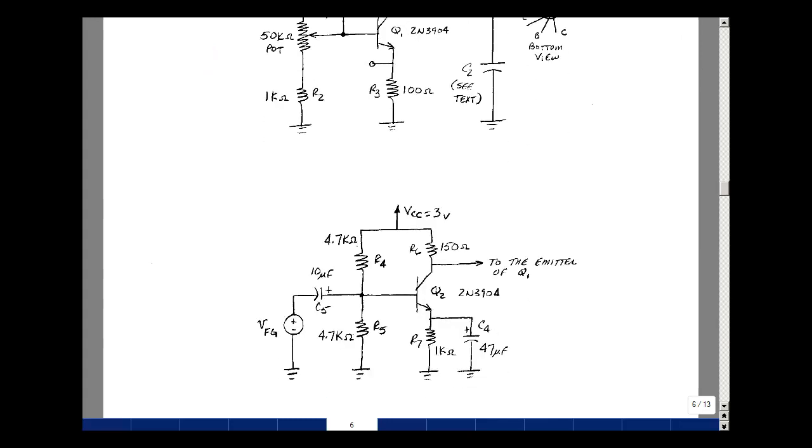It's going to be a simple circuit from ECE 302 where I'm going to pull the signal off of here, not use a blocking capacitor, but use the DC value and then an AC riding on top, which is here to be the function generator, but will eventually be a microphone feeding your signal in. You may want to take a look at this circuit, analyze it before you come to lab, maybe run a SPICE simulation, but you don't have to turn in anything.